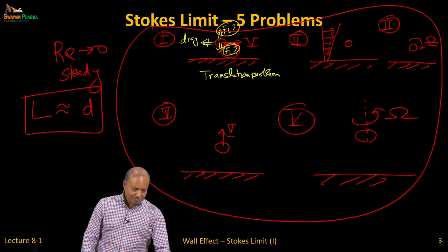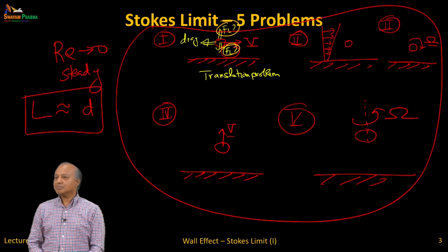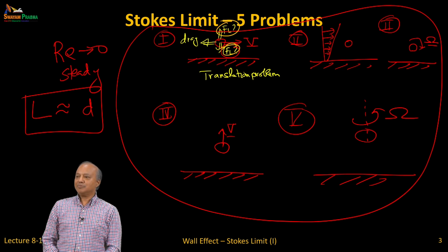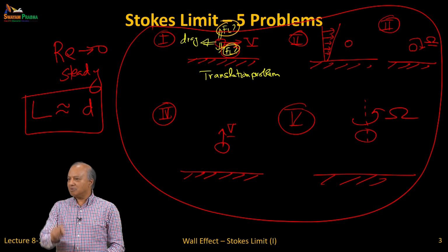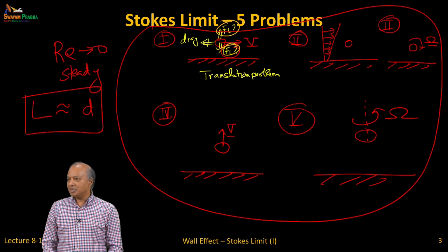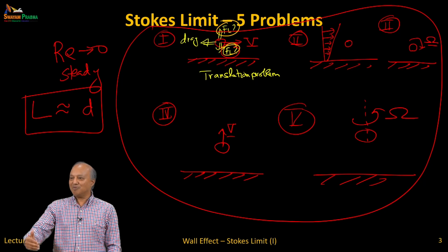So this is applicable only when the Reynolds number of the system is close to 0. This is micron-size particles moving close to a wall in a pipe flow, droplets going in a tube. There are many applications; any microfluidics will be very relevant. For example, at industrial scale, a spray dryer: then this will not work, and I will talk about that later. So let's start walking before we run.